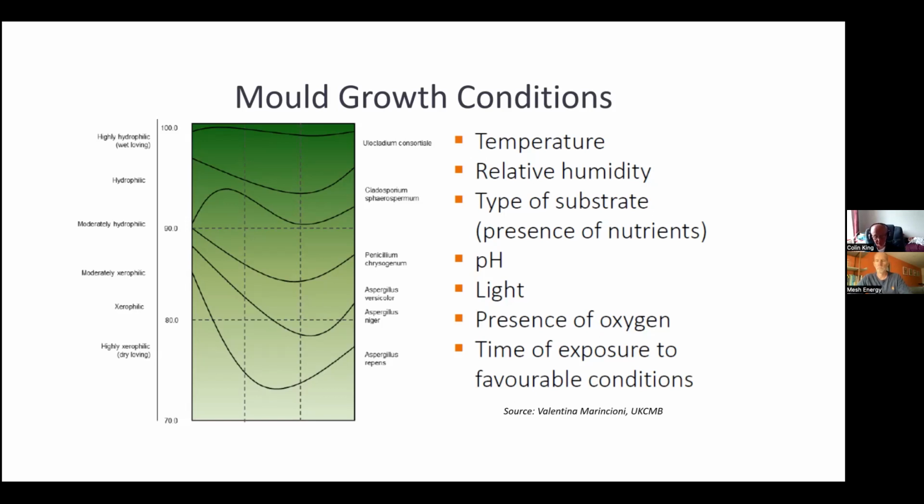But if you look at lime mortar, the normal zone for that can be 12-13% moisture content by volume because of the different types of structure. But brick creams, yes, they can, but they're not a forever solution. There's something that you have to go back to. I think the manufacturers talked about 10 years. When we run the cycles in this report that I'll send you the link to, it looked like 5 years was a more realistic